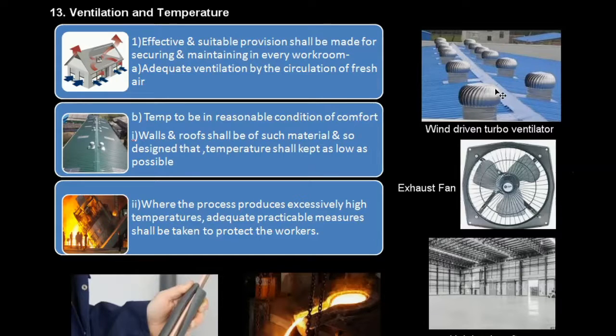While coming out, it will rotate this turbine. Plus there will be outside wind flowing, which will also add to this, and the turbine will start rotating. In this process, the air present below the rooftops inside the factory will be directed from inside the factory to the surroundings, and will then be replaced by fresh air. This process will continue. So this could be one method.